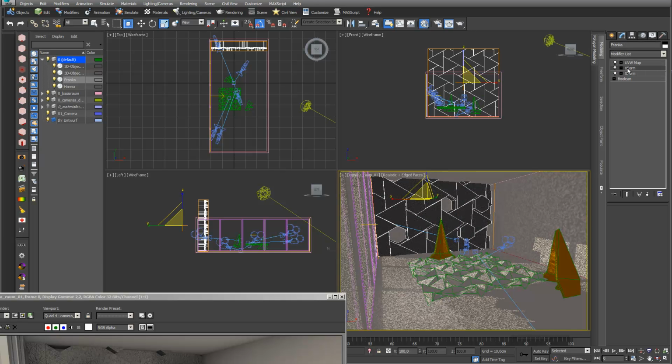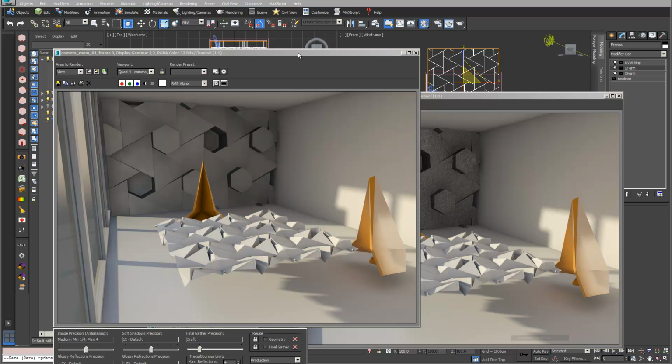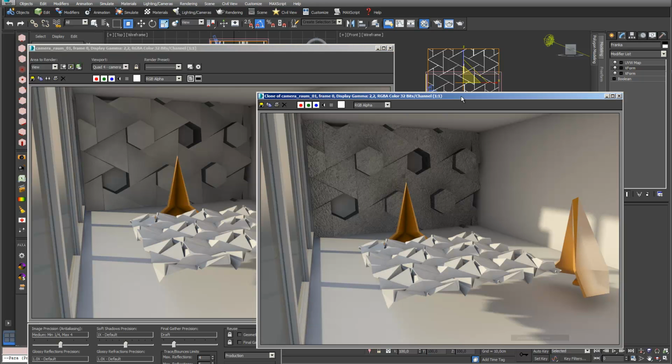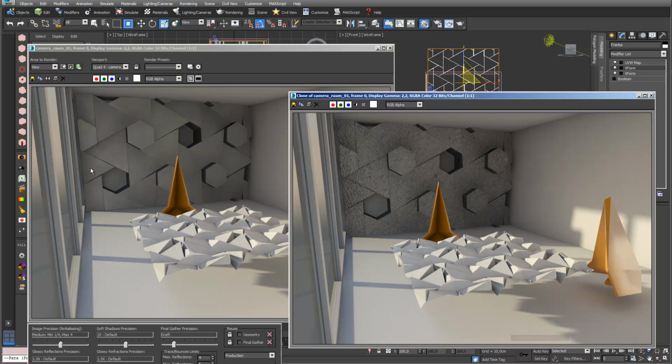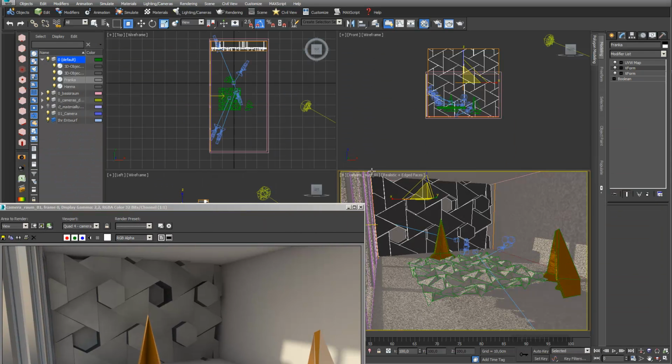If I put this X form underneath my UVW map, then it already looks much better, because my material is related to 100%, and so it's much better in terms of dimension. Okay, here we go. This already looks much better. This is with my X form after my transformation, and this is without my X form, and so that's a much better result. And finally, I show you very few other things.